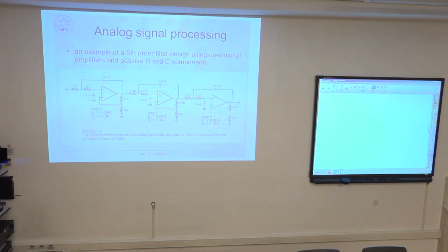And what you want to find out, what will happen with the transfer function if you allow these values to change by random value plus minus 5% of the nominal value. And through this simulation, you could easily find out, okay, the characteristics has changed, the cutoff frequency is not 1 kilohertz, maybe it is up or down. So it was used only for this purpose.